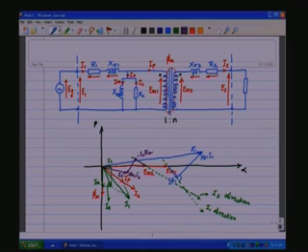Though in the completed form the phasor diagram looks complex, it is not so. You can start from the idealized transformer which is how we evolved the circuit, and then the core loss component, the magnetizing component, and then follow it up with the leakage components and the winding resistance components that we added to get the complete phasor diagram of the transformer.